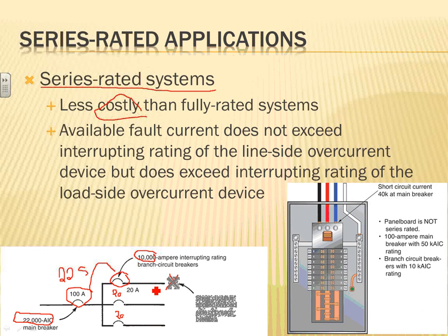No? Do you use fully rated on the branch circuits, receptacles, and lighting? So I thought that's a good example of having interrupting rating. So if there's a short circuit on the line side of the branch circuits, right in here, which one do you think will see it and trip? The main will see it. We're only concerned about the load side of the circuit breaker. On the line side of the circuit breaker, the main 225 amp will trip and interrupt it.